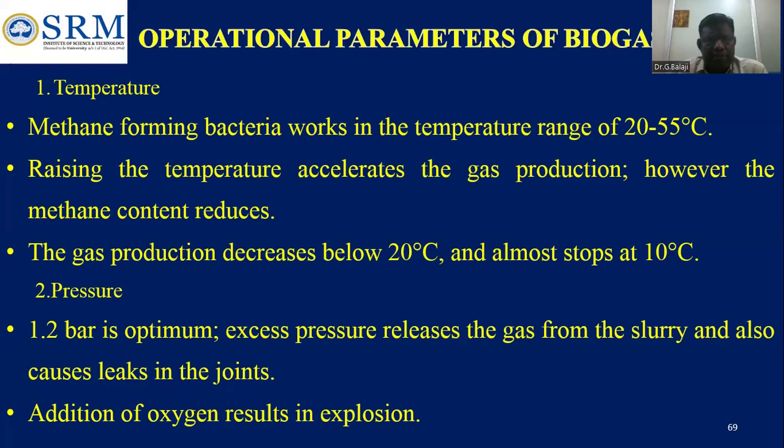The temperature is around 20 to 55 degrees. Above that the gas production increases, but however the methane content will decrease. So it is not advisable to go beyond 55 degrees Celsius.